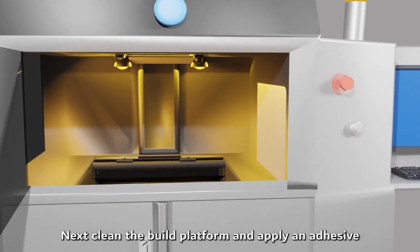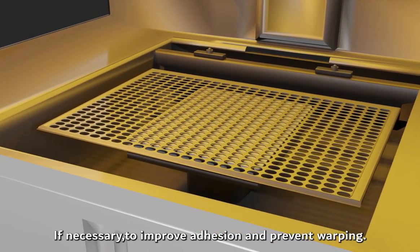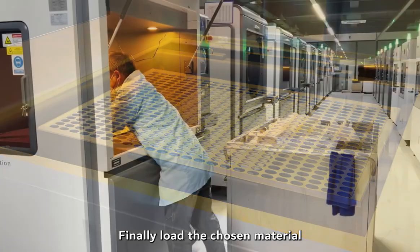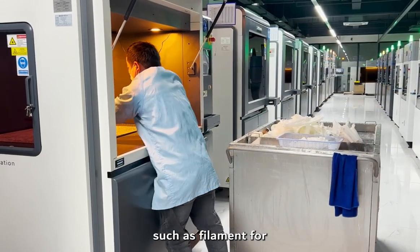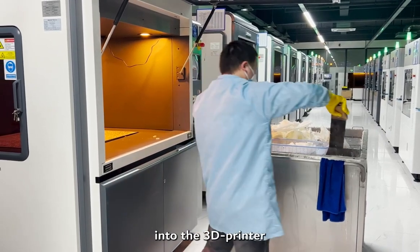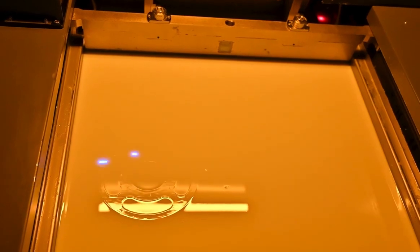Next, clean the build platform and apply an adhesive or surface treatment, if necessary, to improve adhesion and prevent warping. Finally, load the chosen material, such as filament for FDM printers or resin for SLA printers, into the 3D printer. Make sure it is properly fed into the machine.